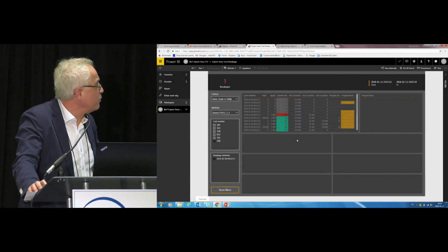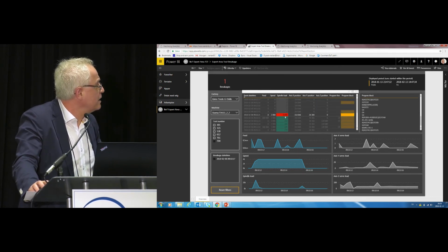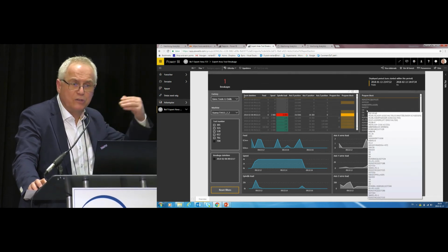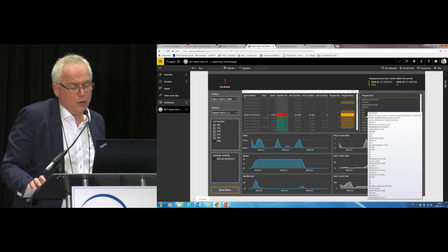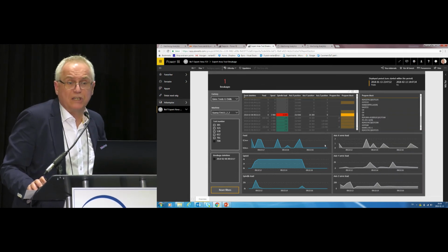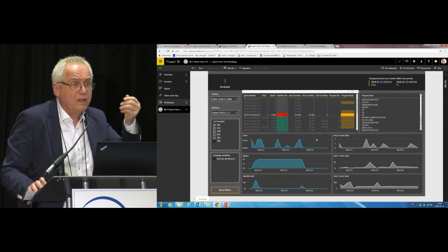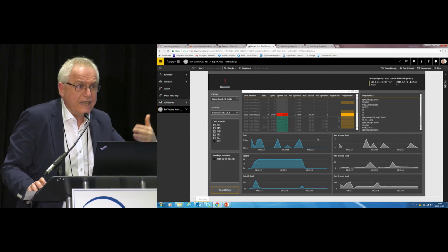This is reading data from the cloud, from the data lake, doing the calculation. This is the calculation we use in machine learning. You can see that there is a tool breakage here. You can immediately check. I can show you exactly what code was running. The NC code the machine is running during that tool breakage. Very valuable information. You can go back to the data and check what data was originally coming before the breakage. What happened after the breakage, nothing to do because the tool is broken. You need to stop the machine. Those kinds of things are where predictive is important.